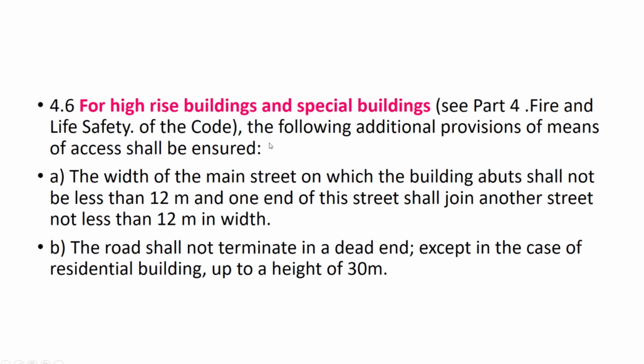ओके ओके. While doing soil exploration, the most commonly used exploration procedure क्या क्या है, is boring. We are doing some type of boring activities in which different field testing procedures are there, like standard penetration test, field vane shear test, undisturbed sample, disturbed samples, location of groundwater tables, field classifications. All these things are required to be done. And many times we are doing something called as open trial pit. Trial pit भी करते हैं अपन.